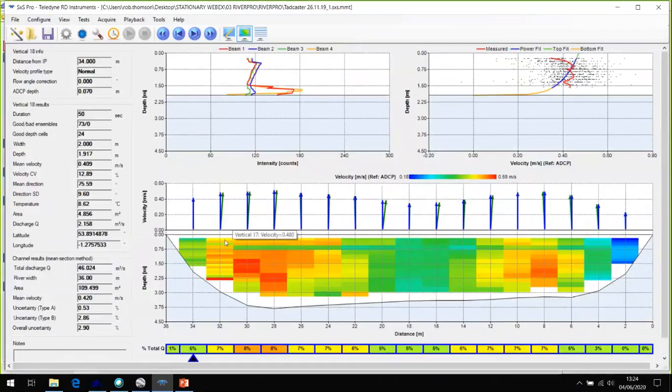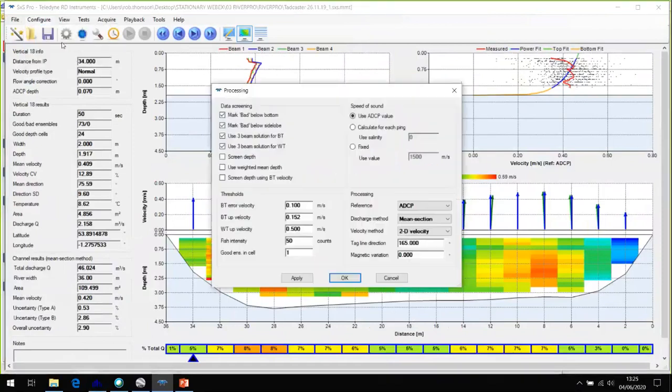So here's the data the SonTek guys will laugh at. But in RDI, all we can do is turn the compass on and off for the whole measurement. We can either have magnitude, Y velocity, which is for snow and ice, under ice, or 2D velocity, which turns the compass on, and we can't apply that per station. So that's a bit of a disadvantage for using RDI.